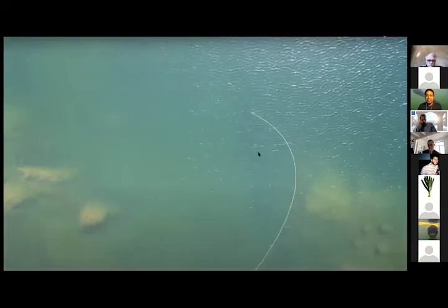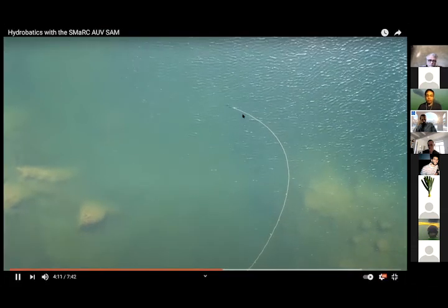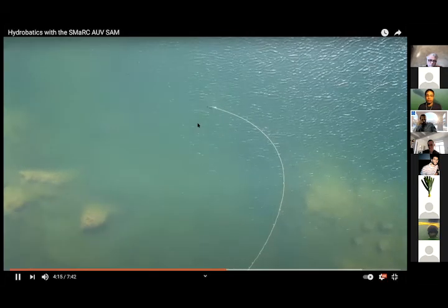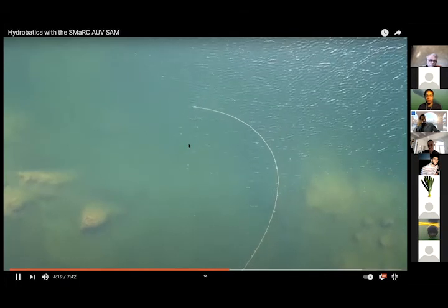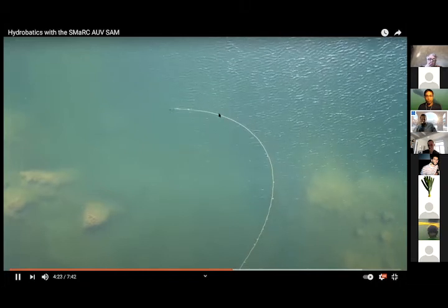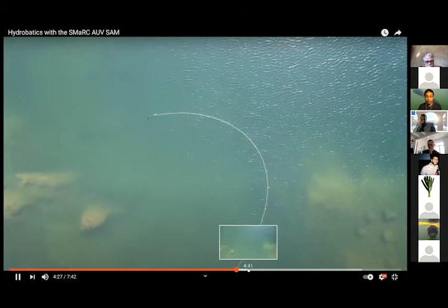In this case, we are only controlling the depth and the heading using the propellers and the thrust vectoring system. And we're not really using the trim actuators during the mission. We're using the buoyancy system for emergencies. So in this way, we're not exploiting the full capabilities of all the actuators, but we're being safe and trying to do something simple in that sense.